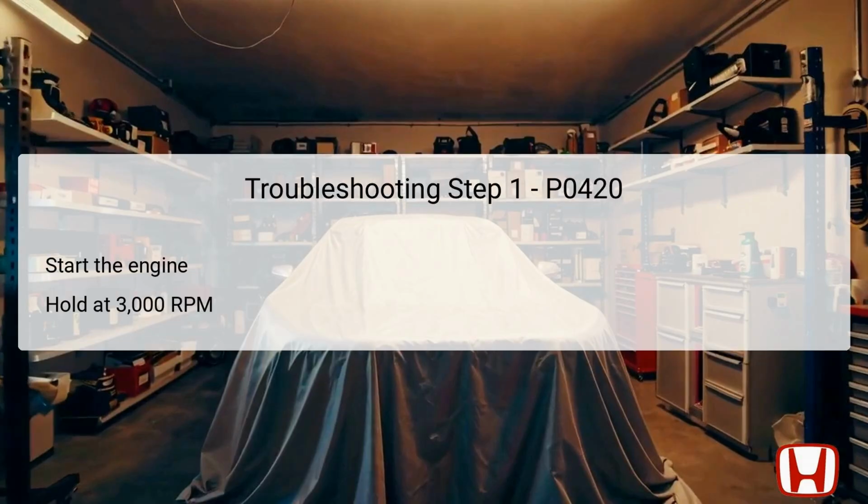The first step in troubleshooting DTC P0420 involves starting the engine and holding the engine speed at 3,000 RPM. This step is crucial as it allows the engine to reach a stable operating condition, enabling the vehicle's exhaust system, including the catalytic converter, to function properly. While holding the engine at this RPM, it's essential to ensure that the vehicle is in either park or neutral if it's a continuously variable transmission, CVT, or in neutral for a manual transmission.